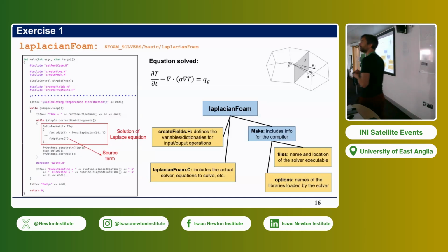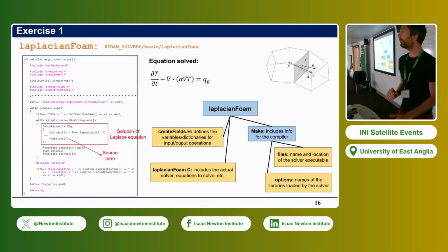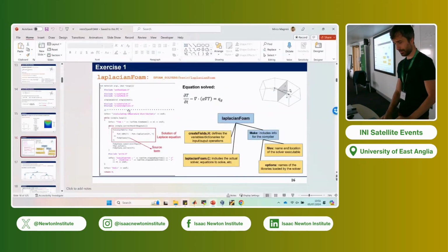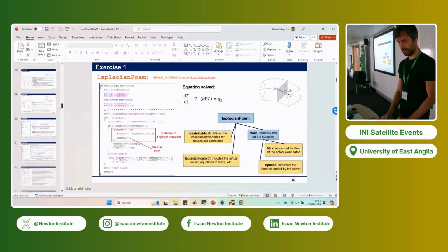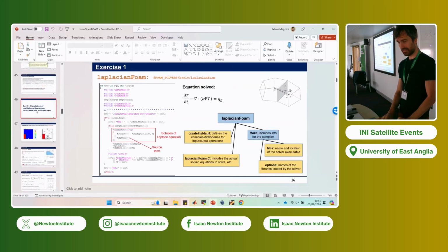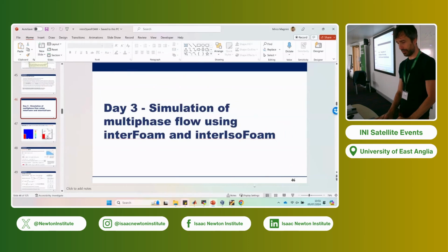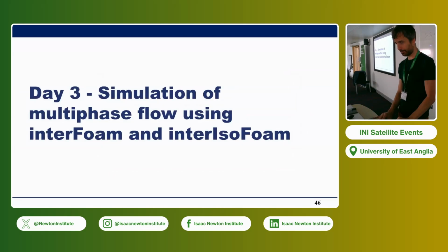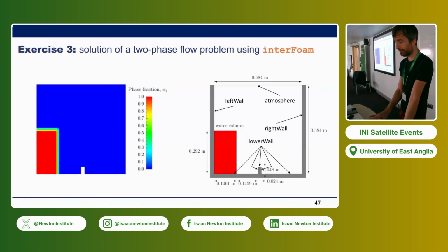Anything else? Okay, I would now move forward to the multiphase flow part. In my slides we are talking of day 3, simulation of multiphase flow using interFoam and interIsoFoam. These are two different solvers for OpenFOAM. interFoam is an algebraic VOF solver, interIsoFoam is a geometric one.